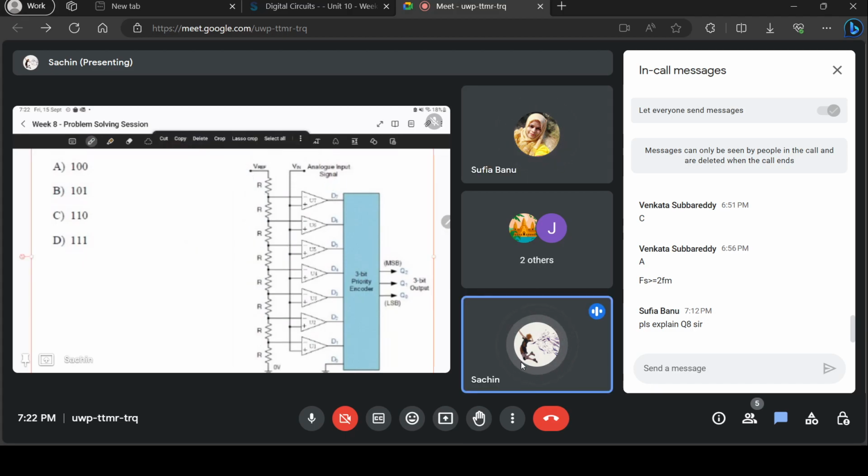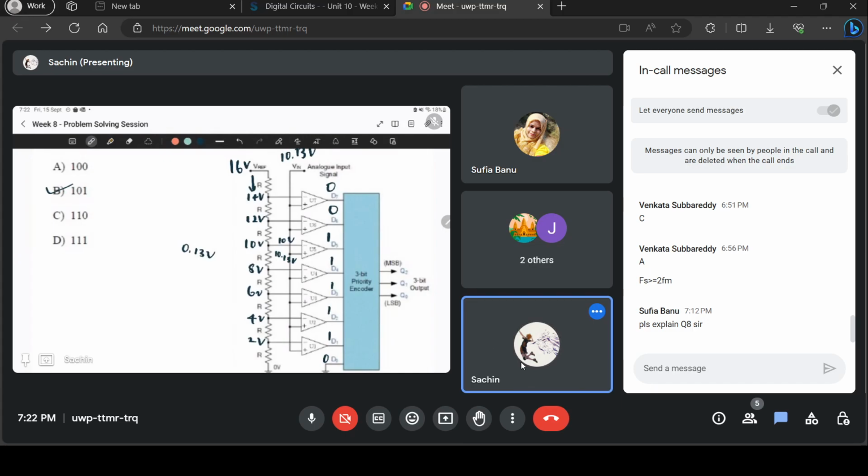Whatever the difference is, you will get a high voltage. It can be just 0.00001 also. Even then it will be the same. Ideally. Practically it might not be able to detect such a small value, but 0.1 and so on it will detect, no problem.